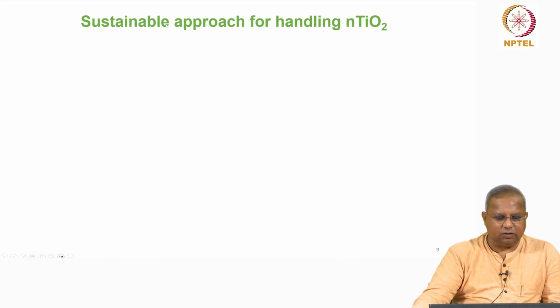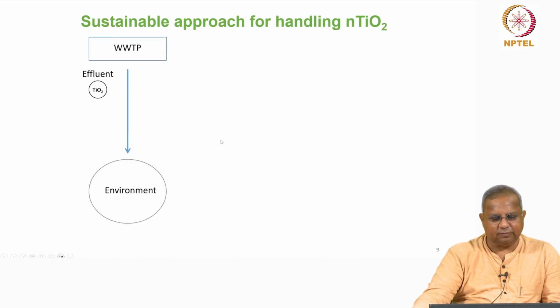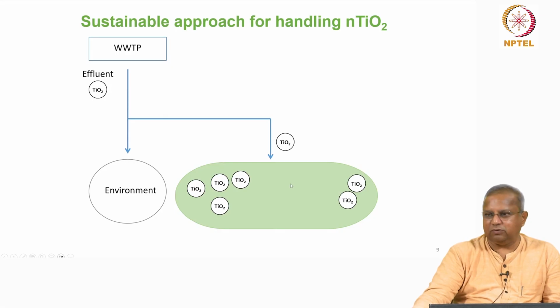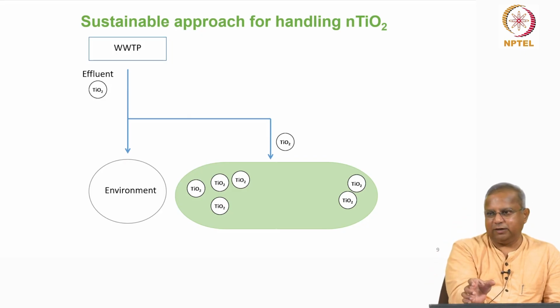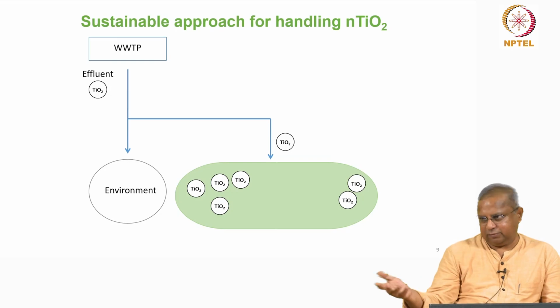So this is what Archana suggested, a sustainable approach for handling titanium dioxide nanoparticles. So instead of it going from the wastewater treatment plant directly to the environment as an effluent, she said we will take this out with the TiO2, rather we will accumulate the TiO2 in some microorganism, bacteria, because they are easy to grow. Essentially set up a column of bacteria and you pass it through that, you can get actually clean water till a breakthrough happens.